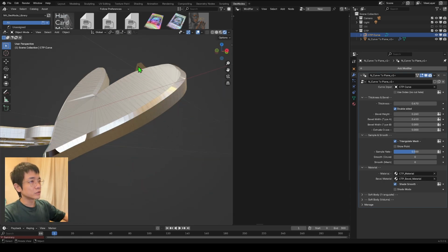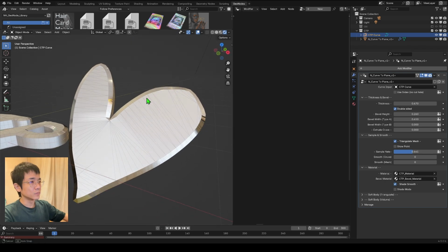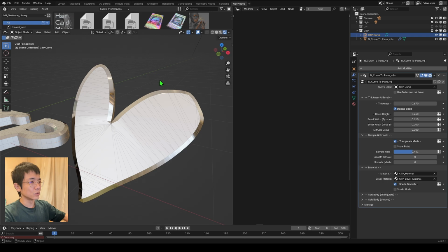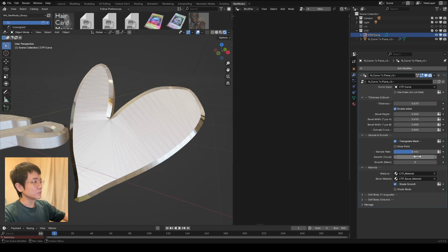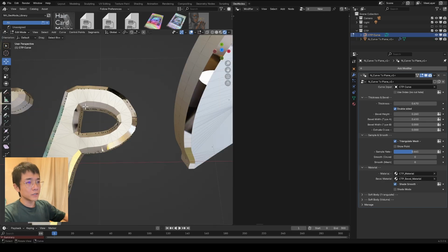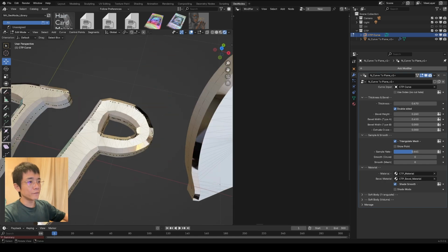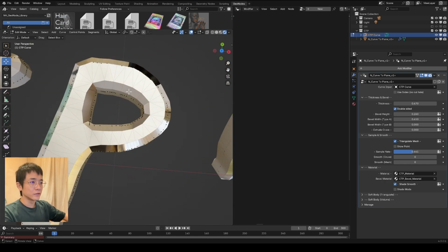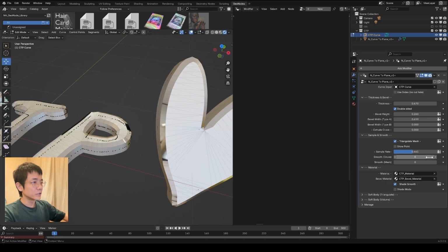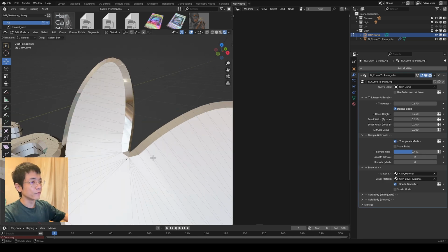Okay, so now there's some problem about this. That's because of the sample rate. So we need to tweak the sample rate a little bit. Make it have a good sample, draw the proper shape, or you can smooth the curve, because the curve, especially on this one, was drawn in poly mode. This is drawn by the poly, and this is drawn by the bezier curve. So with the poly curve, you will get so many points and a lot of jiggling, and so we need to smooth it out a little bit, so make it smoother. Also use this smooth, it will fix this problem.